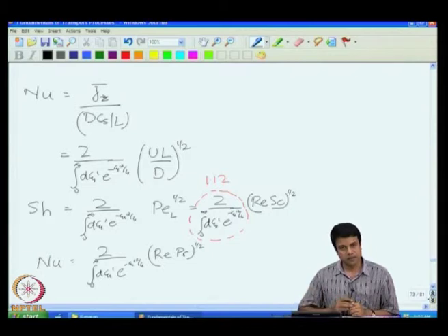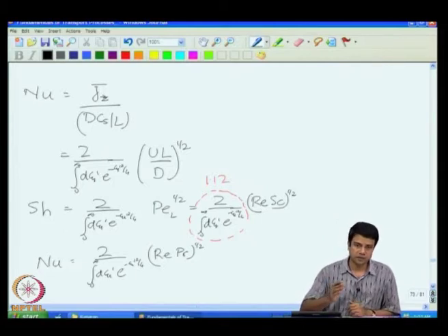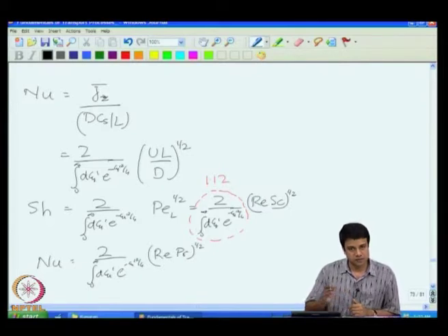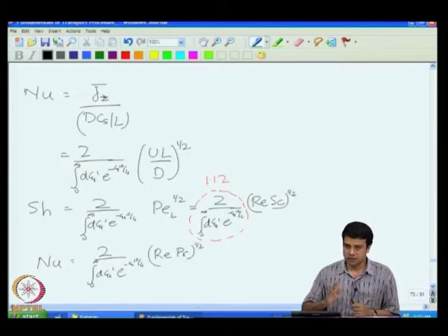And this was once again based on similarity solution, but not on dimensional analysis. We just used the fact that the equations for the unsteady flow and for this situation are exactly the same, the boundary conditions are the same, so the solution is the same. That works for any linear problem. If the problem is linear in the concentration field and you have well specified boundary conditions, there exists a solution, and that solution is unique.